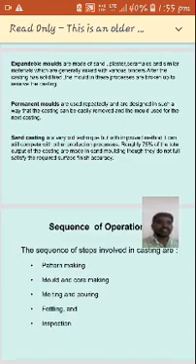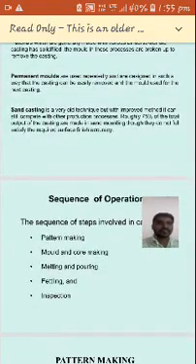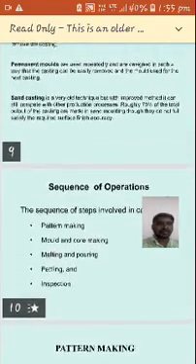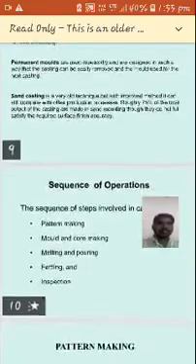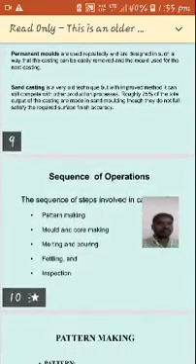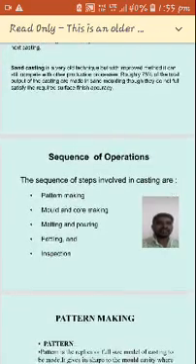Okay. Roughly 75% of the total output of castings is made by sand molding, though they do not fully satisfy the required surface finish and accuracy. So almost all in all, sand casting is preferred. Around 75% of the total output of castings, sand casting is preferred. But there are a few disadvantages: the surface finish is not up to that much. That is a disadvantage.